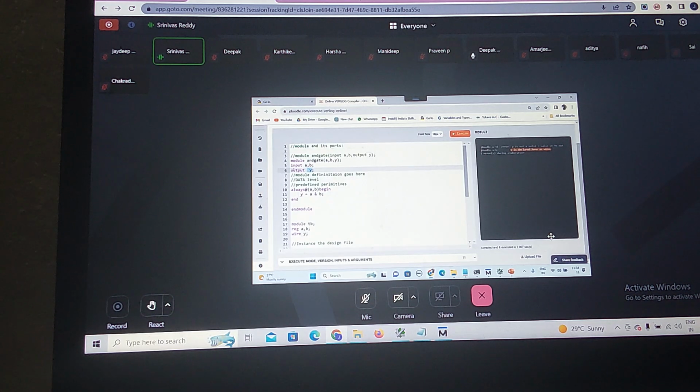Y data. It is continuously run now. It has to store. If you are using an always block, how will this always block work? It is like a continuous loop. An initial block will execute only one time during your simulation, whereas an always block is executed continuously. So whatever variables I use in the always block should be declared as what? Reg data type. Reg data type. Now I will be getting the output for this code.